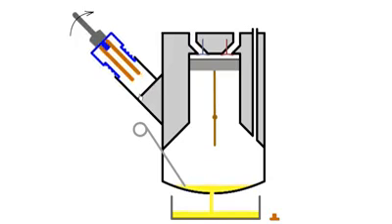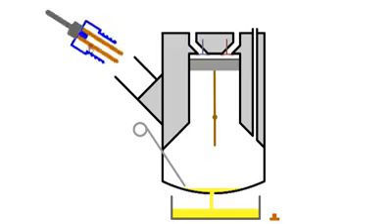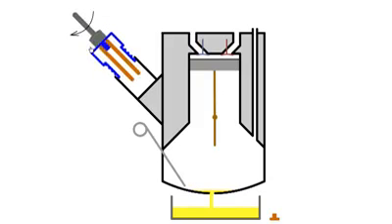When the filter housing is unscrewed, a hole opens in the housing and allows the oil in the filter to drain internally to the sump. The element contains no metal parts, it's manufactured from paper and plastics, and is suitable for incineration, capturing heat from the waste oil. The new filter and O-rings are fitted, and the housing is tightened to the correct torque.